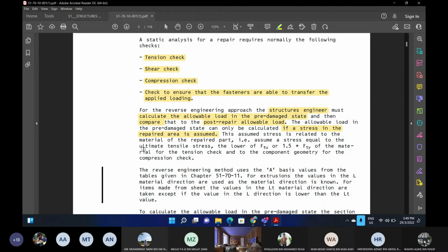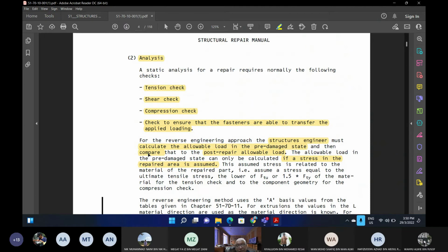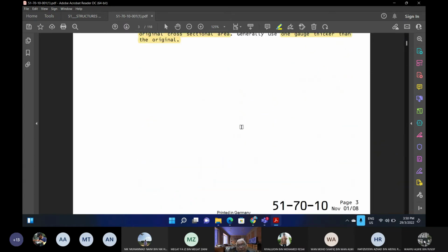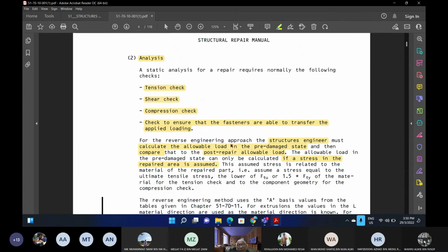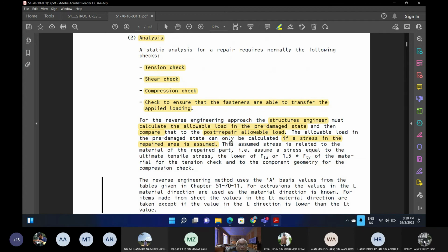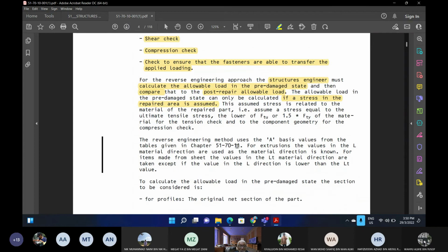And also you can calculate the stress of the material. You make the doubler, times the cross-sectional area, which is the thickness of the doubler, and then that is the load that the doubler can take. So the load of the doubler over load of the original, and then you will get the margin of safety, factor. Sorry, what do you get? You got 3 items I was discussing with you. You will get reserve factor. And then reserve factor should be more than 1. Okay, clear?